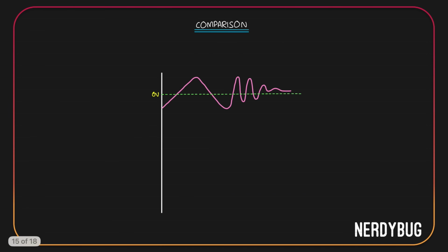Let us take a random signal and compare the output of a normal comparator and a Schmitt trigger if this is given as an input to both of them. If the applied Vref is 0, for a normal comparator, the reference voltage will be 0 volt. Every time the input signal crosses 0 volt, the output will switch. Comparator output will look like this.